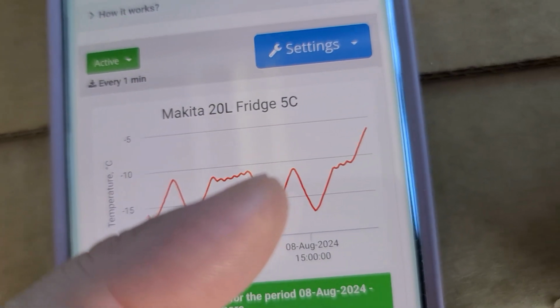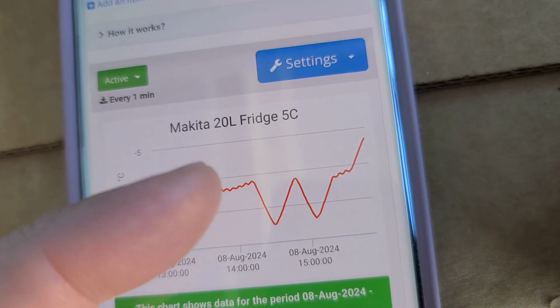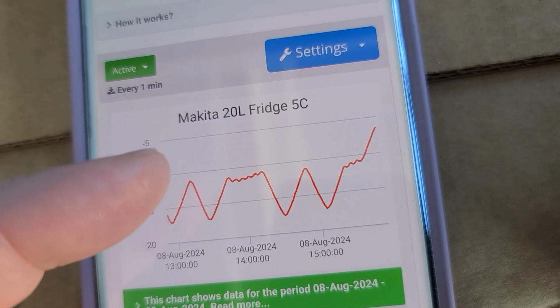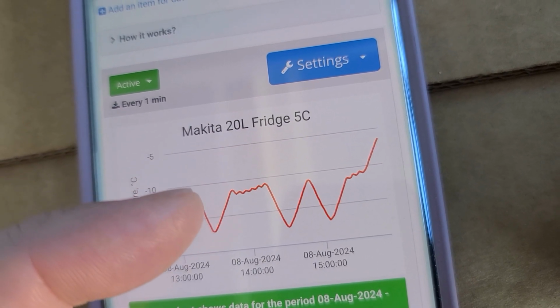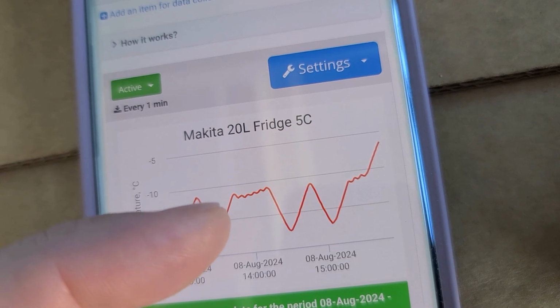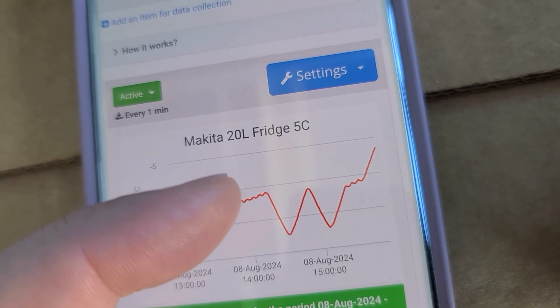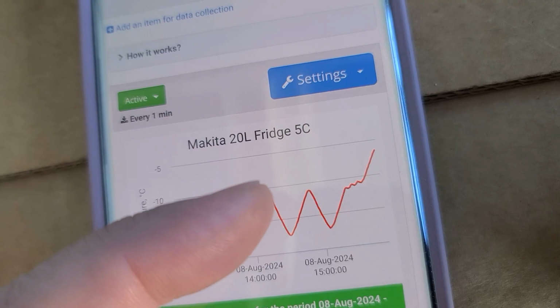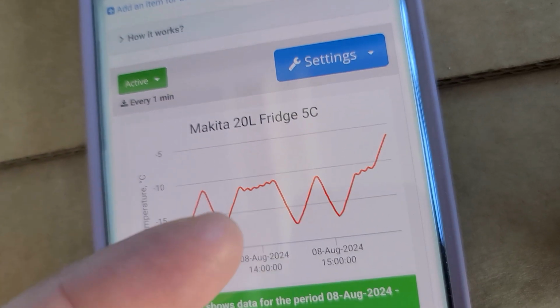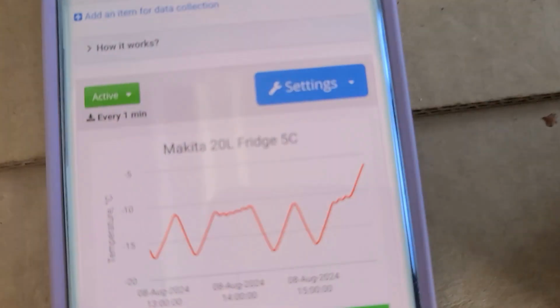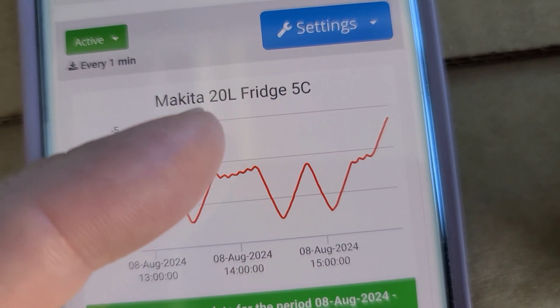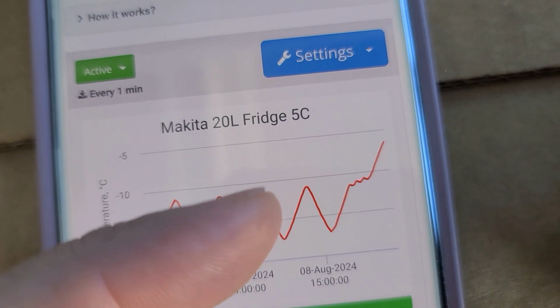Definitely it cannot cool, so you can see, compressor stop, compressor start cooling, stop, trying to cool, and no. Then the battery probably got some power, and it again can cool, but next time again cannot cool.